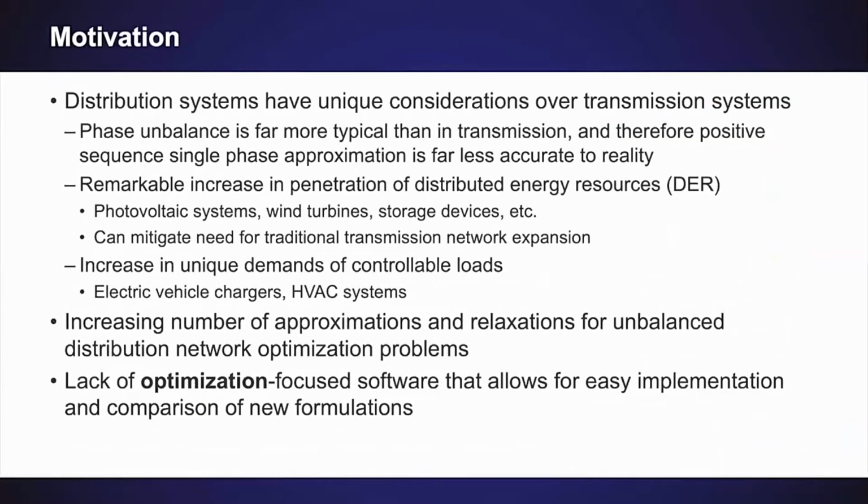So there's quite a few different motivations for the creation of PowerModels Distribution. First, distribution systems have rather unique considerations over transmission systems, making existing transmission-focused software for optimization inadequate. For example, phase unbalance is far more typical in distribution systems, and therefore the positive sequence single-phase approximation commonly used in transmission systems is far less reflective of reality.